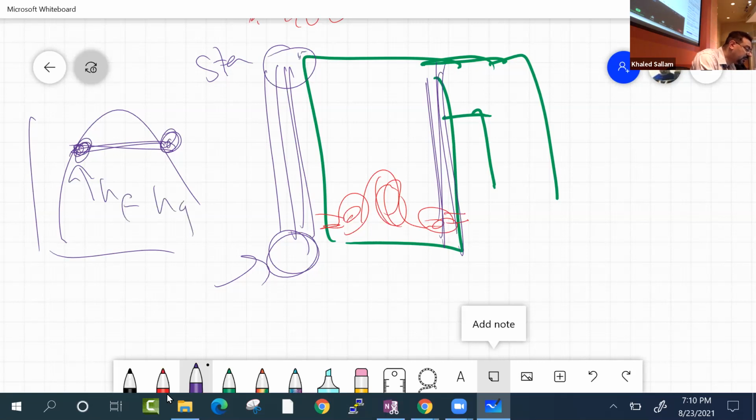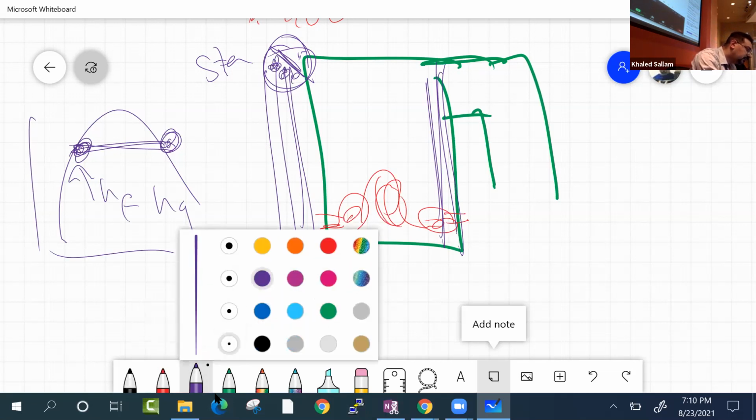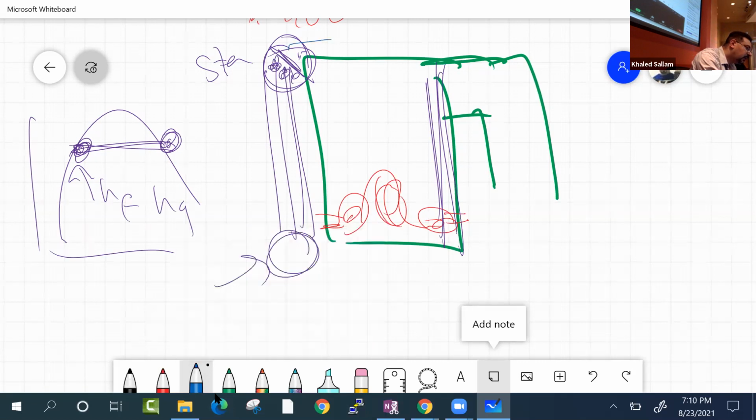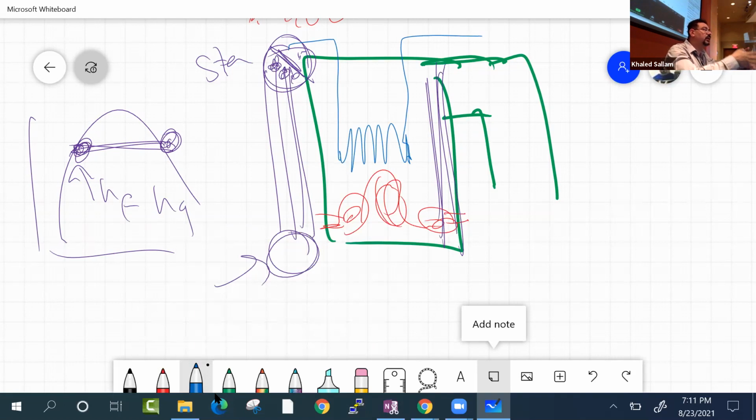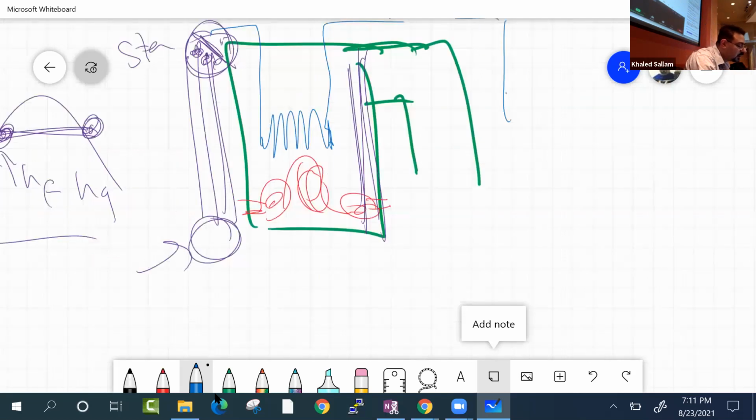Once you have steam out, there is something called the steam trap over here that takes only the steam out and lets all the droplets that didn't boil all the way go down again for another round. They take that steam and send it to the superheater, which is basically a heat exchanger that is directly on the fire. You know, when you do grilling, that's the one that has the direct heat on top of the flame. And then this goes to the high pressure steam turbine.